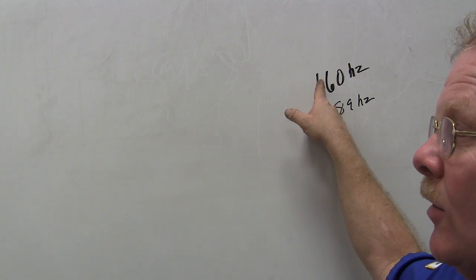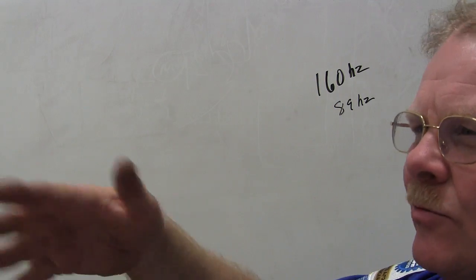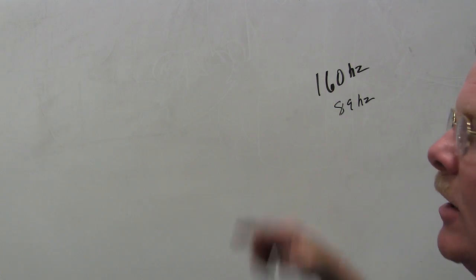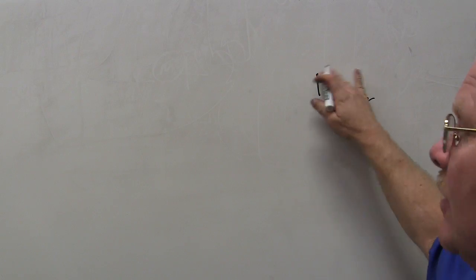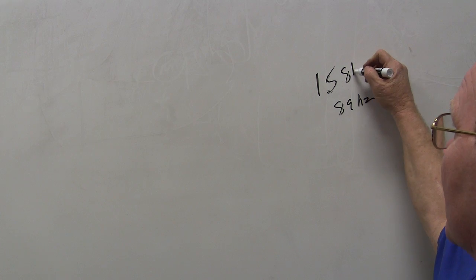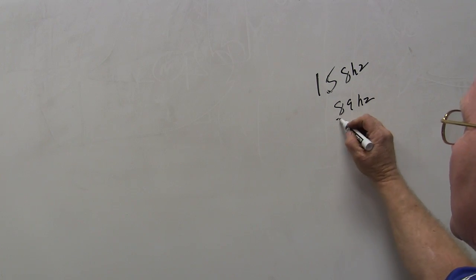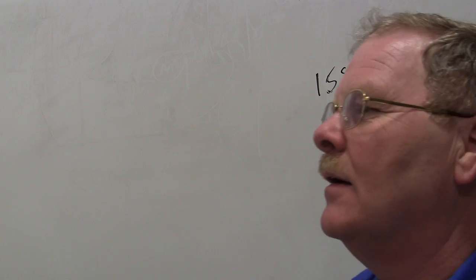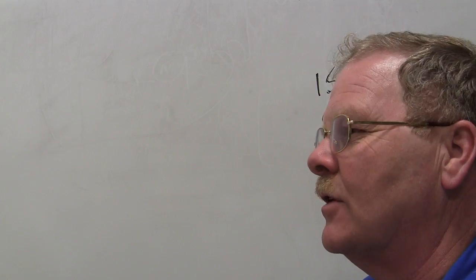So I went to the Bronco and measured the one on the Bronco, and on that particular day, and it's going to vary from day to day as pressure varies, it was like 158 hertz. And this one here was 89. Well, right away, comparing a good one to the bad one is a good way to do that.